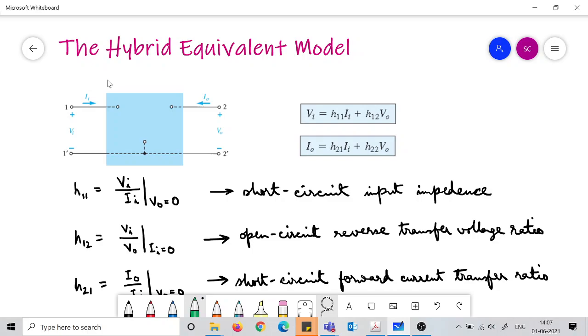The parameter is simply the RE resistance, and that is calculated as 25 millivolt divided by IE. The other parameter is the beta or the alpha, the gain. And of course there was the output resistance RO, which is the slope of the collector characteristics curve, but that is quite high and often we neglect that resistance and consider it as an open branch.